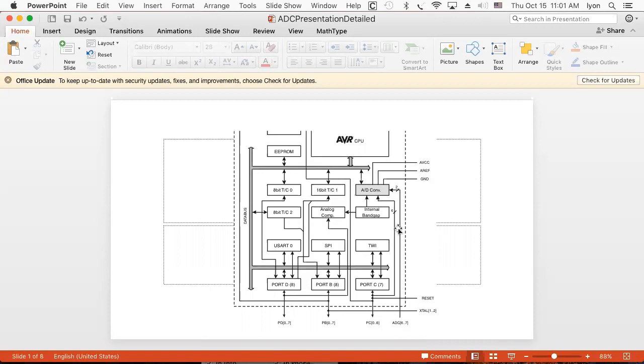They're tapped in and going over into the ADC converter. We can also use them as digital I/O ports, should we like to. We set up our data direction register for that, but right now we're just interested in using them as an ADC converter input. And that's the focus of yesterday's lab. We were able to digitize from the ADC converter and then output to our little SPI DAC, and we did that in real time, changed our scaling rates for the sampling, and then proceeded to observe aliasing effects for different frequencies from our oscillator onto our oscilloscope. And that was all very educational and fun.